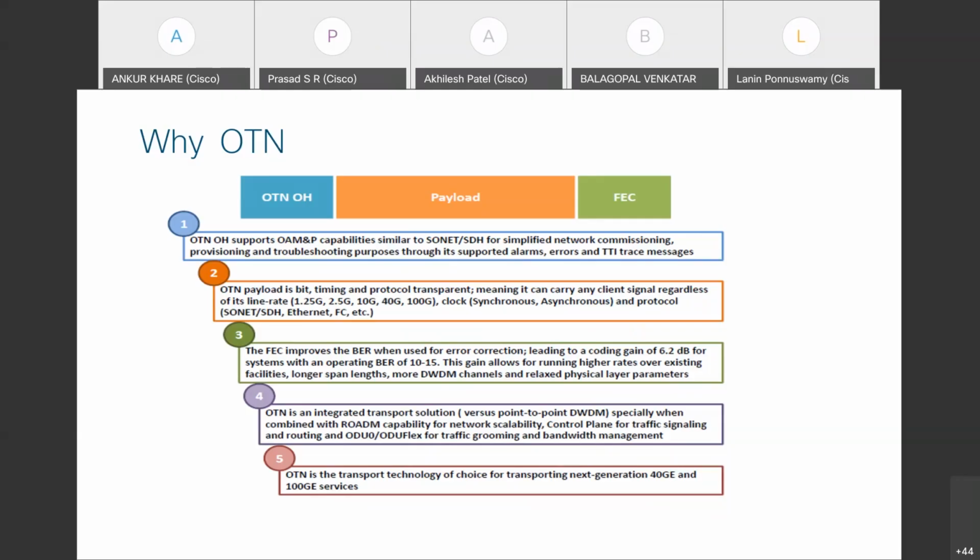Okay, in Ethernet you might not have as many alarms as the optical network has, because in the optical network, we don't go within the data and we are not worried about the data within, right? We just rely on the overheads. If the overhead bytes are correct, we don't have any alarms in the network. We consider the layer 1 physical link is up. Okay, so